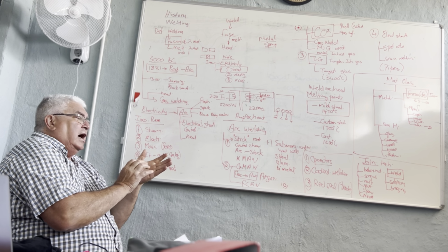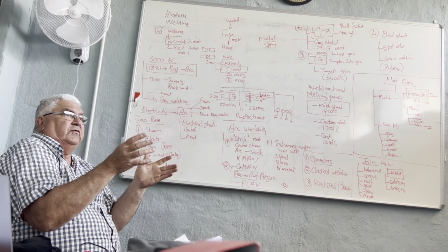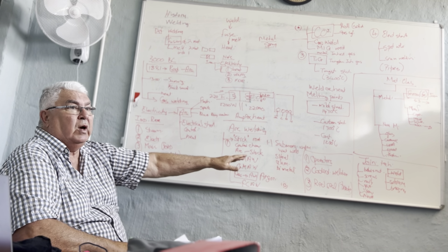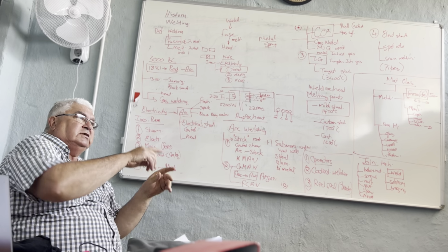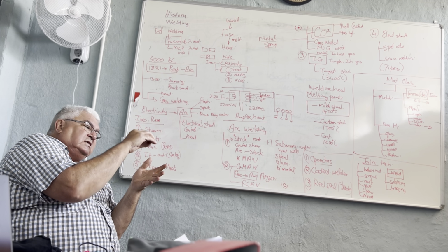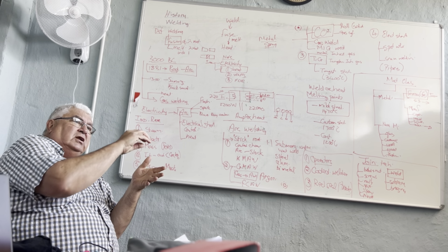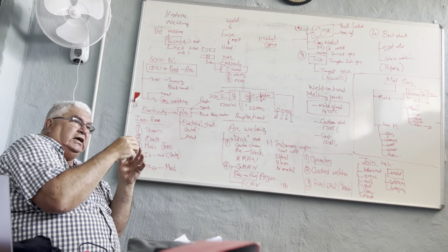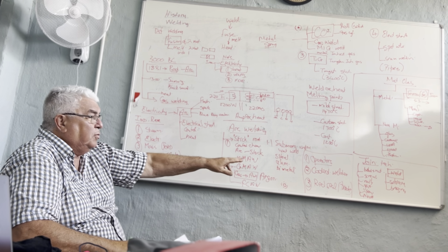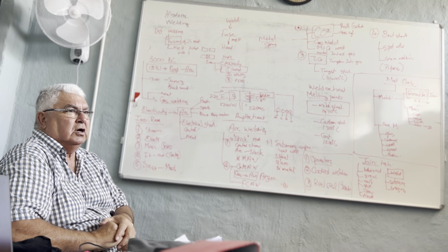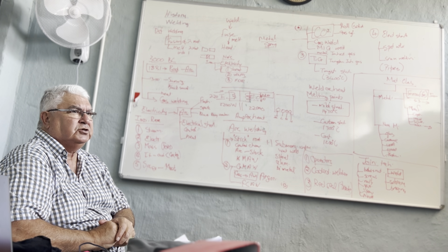That means I can produce 1,000 of an item at the welding procedure. We call it a welding procedure. That means there's a procedure, say step 1 do this, step 2 do that, step 3 measure that, set the machine like that, step 4 keep it like that. And you test it and you certify that, you become a coded welder. You weld a specific code. Code is a prescribed procedure on a product.